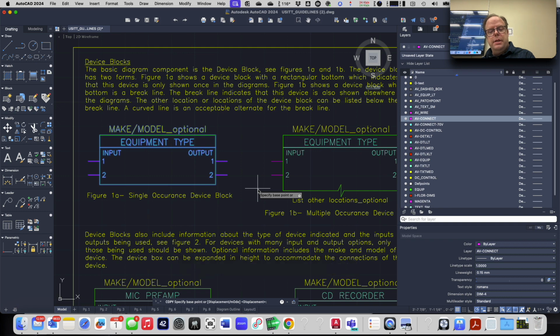And the dynamic input that we turned on has now moved the prompts that are down here in the command line up so you can see them right next to where your crosshair is, which saves you a little bit of looking up and down. So it'll move up next to what you're supposed to do right now. And what it says is specify base point, or there are some options.